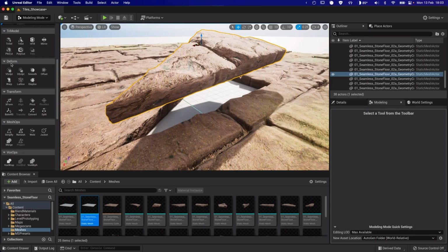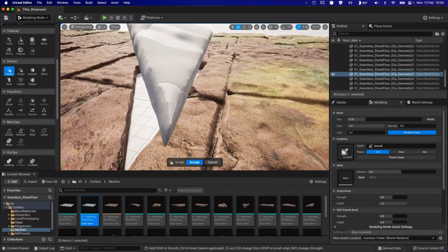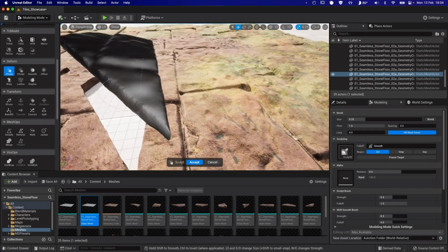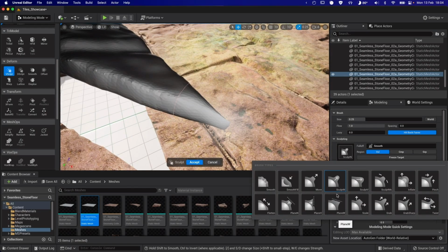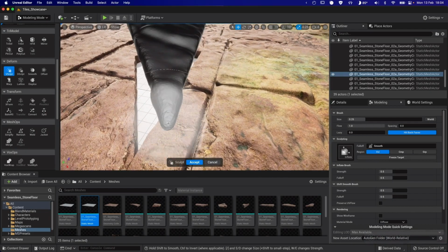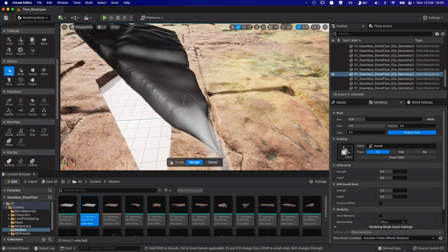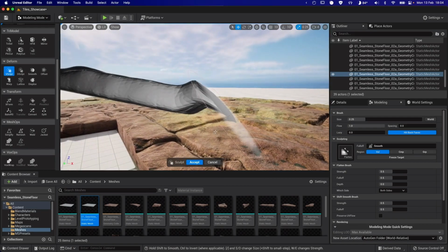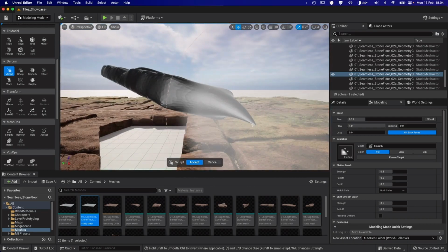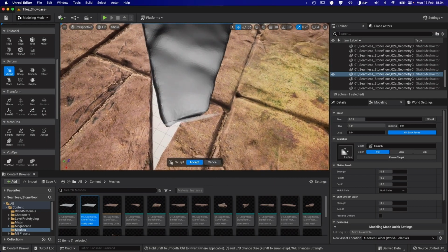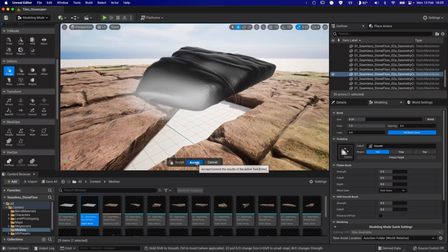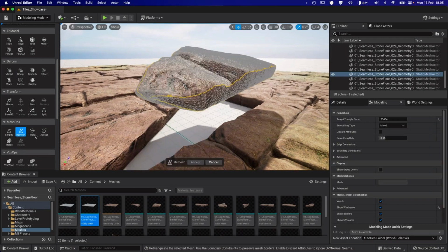You can also do some sculpting. For example, our front is very pointy and I want to make it a bit more smooth. And in order to do that, you can actually do a bit of sculpting, similar to the way Blender works. Just select the inflate brush to inflate the mesh, and then just press Shift to do the smoothing on top of your inflated mesh. If that doesn't work, you can try to do a flatten on that portion and then try to smooth everything back to a better value. I find this process a bit tedious and I don't usually bother to do it very much.